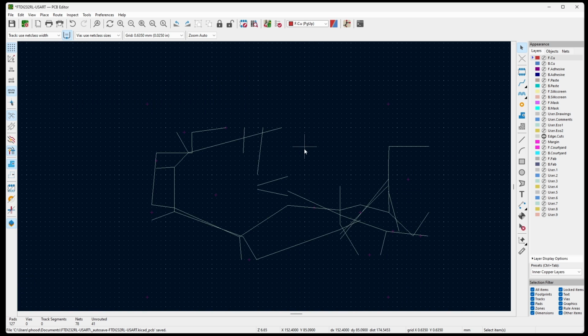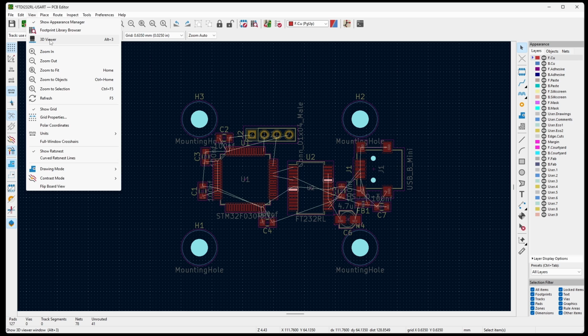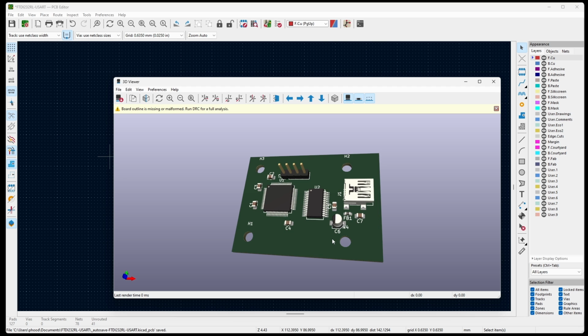The edge cut is a really important one because that shows the limits, or where the board is going to be cut by the PCB manufacturer. If you look at what the board's going to look like before you put those edge cuts, it's just going to create its own edge cuts around the boundaries of where all of the components are arranged. So when we create our own edge cuts, it will change where it thinks the boundaries need to be.